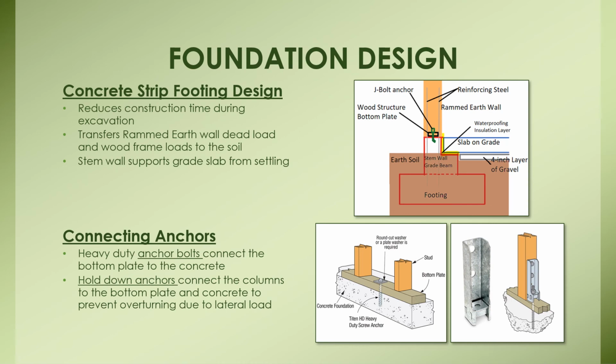For the foundation design, concrete strip footing design was selected. It reduces construction time during excavation. It transfers rammed earth wall, dead load, and wood frame loads to the soil. And finally, the stem wall supports the grade slab from settling. As for connections, heavy-duty anchor bolts connect the bottom plate of the wood frame to the concrete, and hold-down anchors connect the columns to the bottom plate and concrete to prevent overturning due to lateral load.